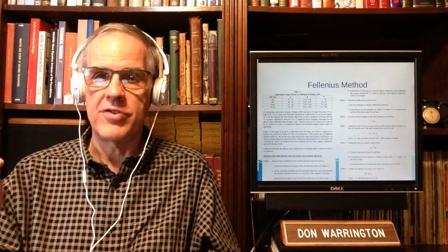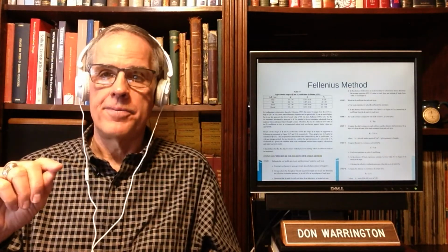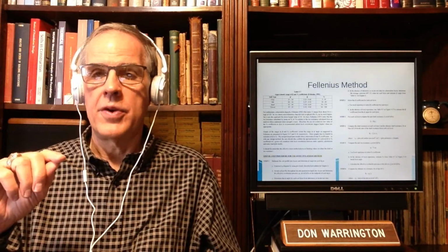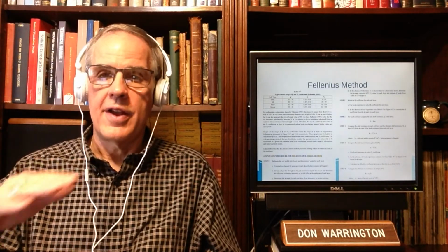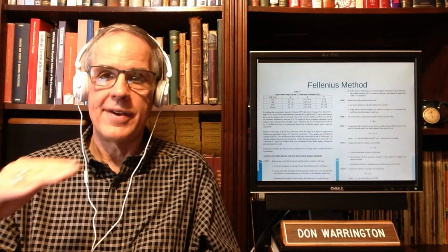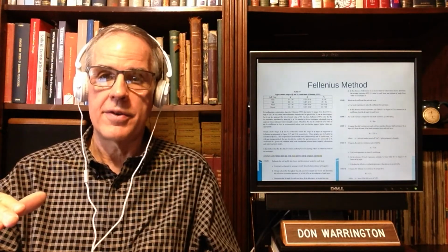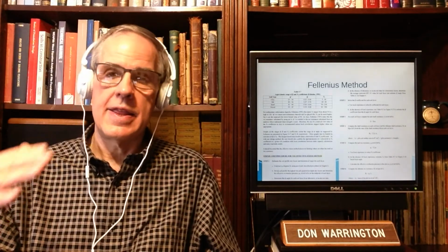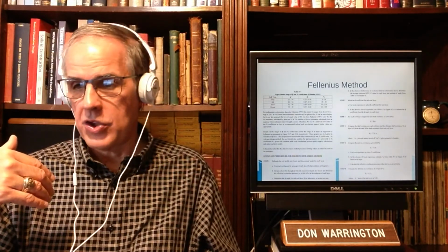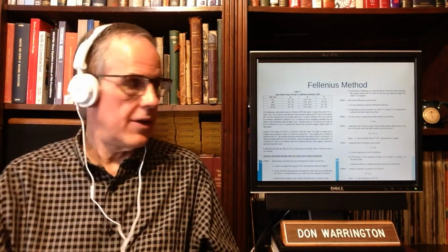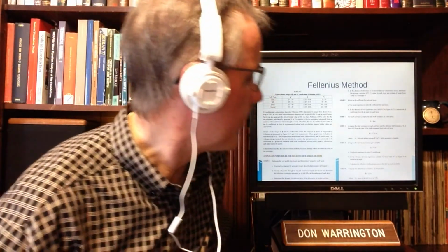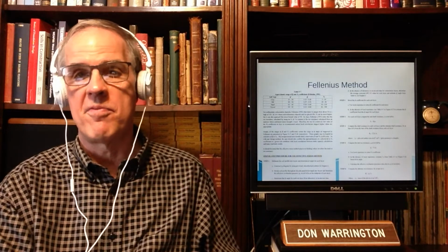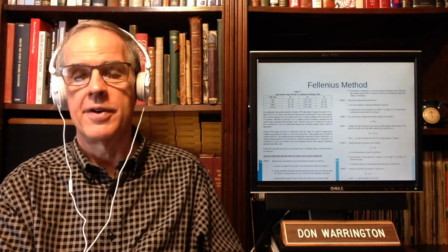You take it in the middle, just like you did when we were working with cohesive soils and consolidation. Remember the middle of the layer thing? Well, guess what? It's come back to haunt us. And the qt at the toe is equal to the effective stress at the toe times some bearing capacity factor.